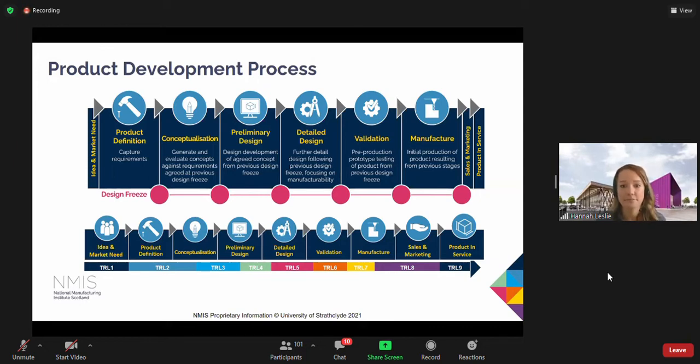In preliminary design, the chosen concept goes through verification checks and initial verification to establish that the concept can perform the intended function and possibly optimize the geometry a little bit at this stage. This is where you'd also start your CAD modeling in earnest. In detailed design, the focus is on manufacturing and materials for the concept, moving it into a state where it can be manufactured through the production of general arrangement, GA, drawings, and bills of material, and so on.